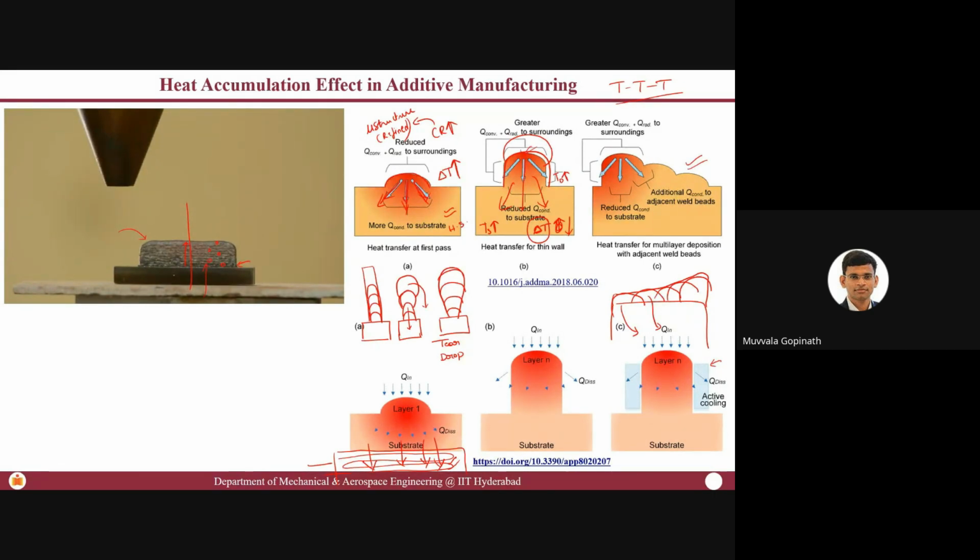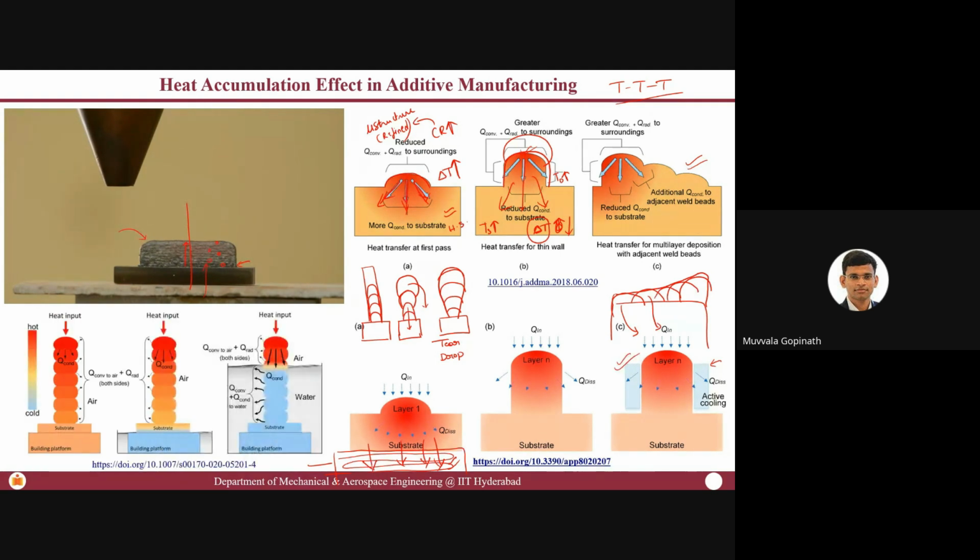Of course, people have done it without this passive and active cooling. They have used fins or fans and tried to cool it. Of course, there are extreme methods where the entire deposited component keeps entering into the water, so that whatever is deposited always stays at room temperature or the temperature of the water.